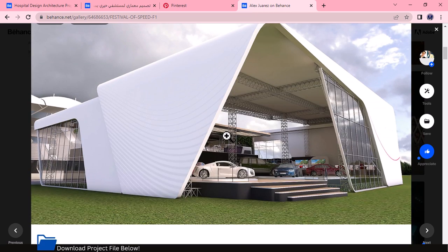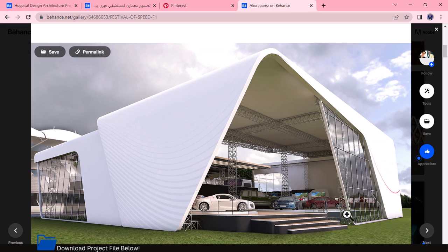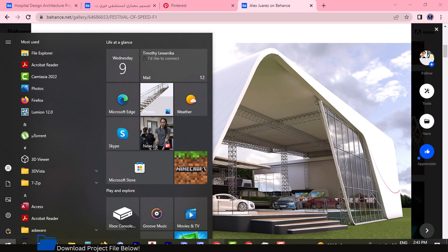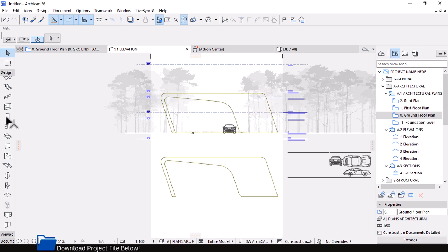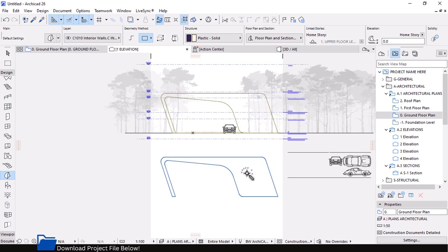It's defined clearly on this elevation. So by using a complex profile, it's going to be difficult for you to get this. Hence, I've chosen the morph tool. Let's activate the morph tool and then click on the boundary by pressing and holding the spacebar key. Your magic wand cursor will be active, and then you click on the region like that.